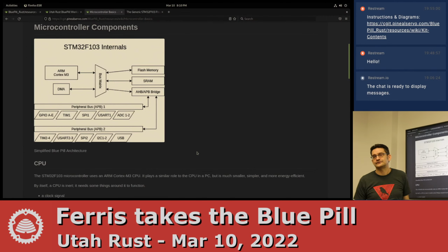We won't be covering any of those right now, and there's a caveat with using USB: a lot of these boards have a manufacturing issue where they put the wrong size resistor on some of the USB lines, and that makes some USB ports unhappy with it. If I'm not mistaken, we tested these and found that they do work, correct? I'm pretty sure we tested for that problem and found that only one out of the first batch didn't work.